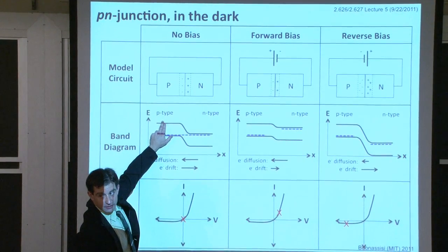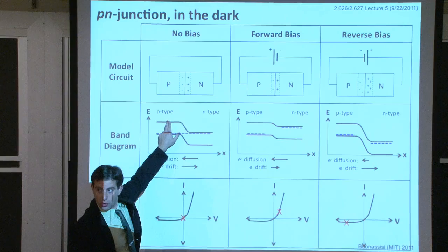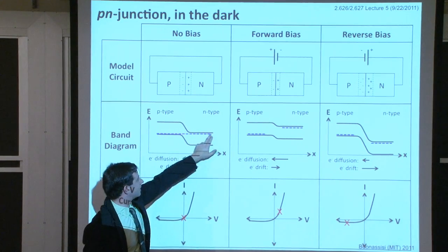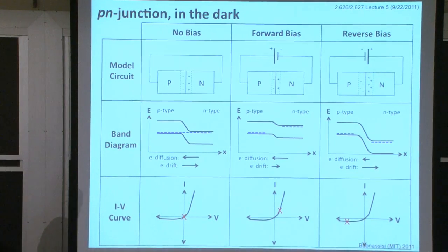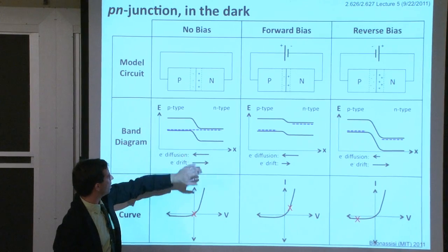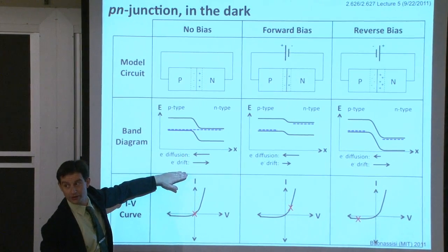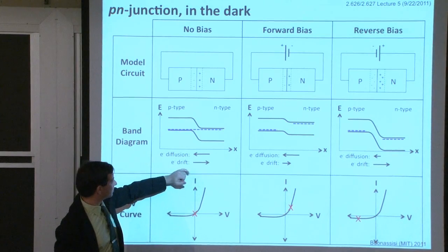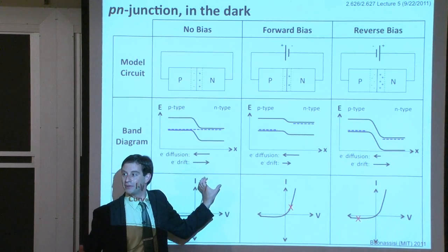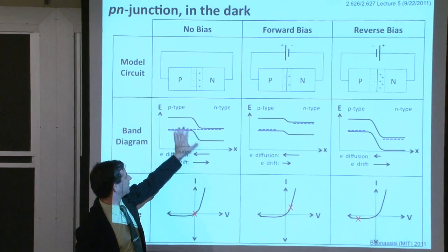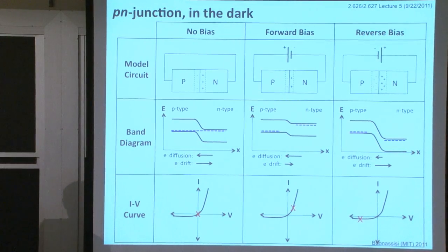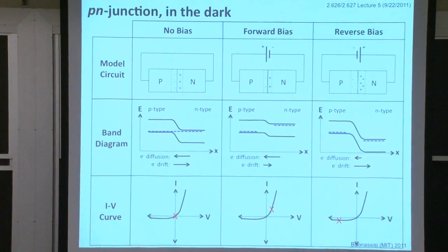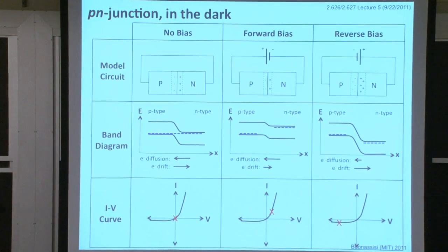What will happen to those electrons now that they're in the conduction band? Where will they want to go? To the right, right? Okay, so what you'll do is set up what's called an illumination current. Notice now at the bottom of the second row here, you have electron diffusion, electron drift, and IL current. IL stands for illumination current. So you have a third arrow here that will have to be implemented in some way. And that will, by the principle of superposition, you should think what happens to your IV curve as well. So let's make an estimate of what we think should happen. Then I'll confer some notes, and then we'll measure what actually does happen under illumination. So why don't we give it a shot?